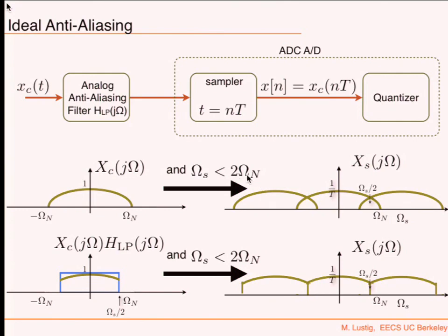So in order to avoid the aliasing, you run your signal through a low-pass filter that filters out the high frequency that would alias, and now the signal is band limited to the bandwidth that can be represented by the rate that you're sampling. And you don't get aliasing anymore.